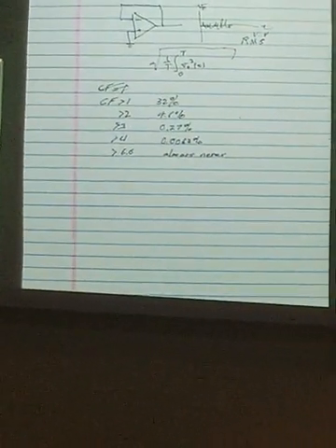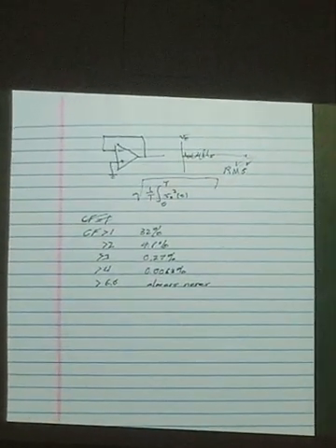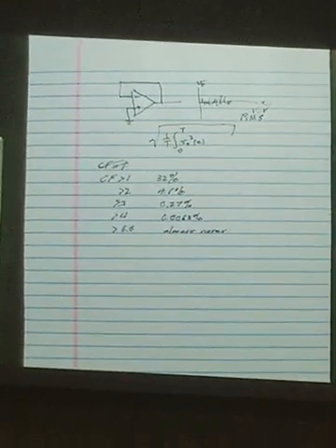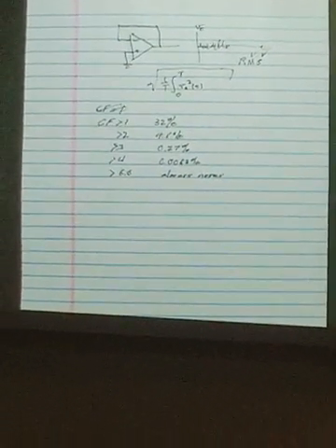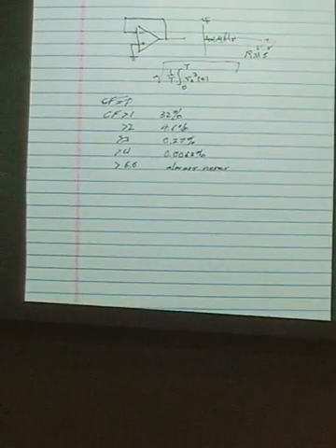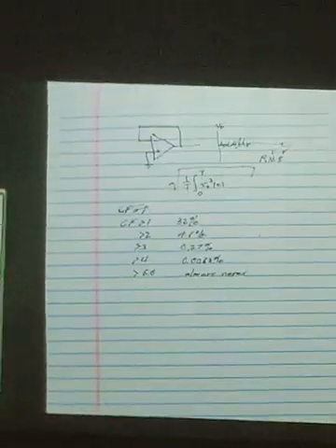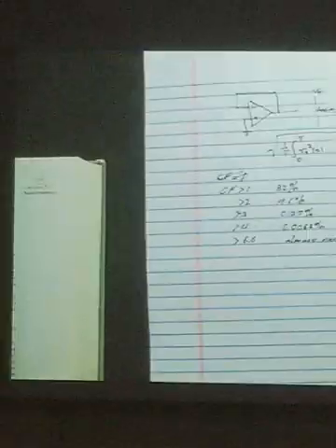What about things like transients? Oh, you can always blow things up with transients, yeah. The answer to that is yes. So my question is, do you recommend us designing a protection for the ADC? No. There are people that are really good at that, and they already put it on the chip. So I would leave it at that. I mean, the old days of putting Zener diodes everywhere as sort of input protection, we don't do that. Okay?